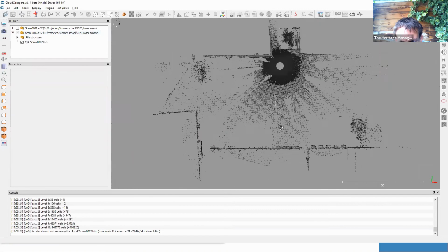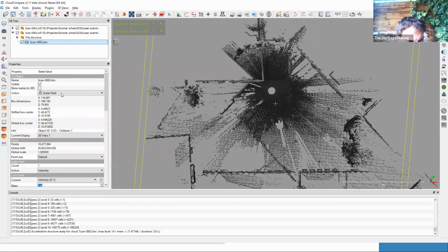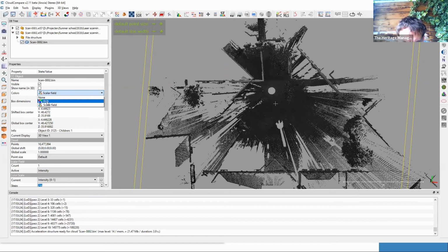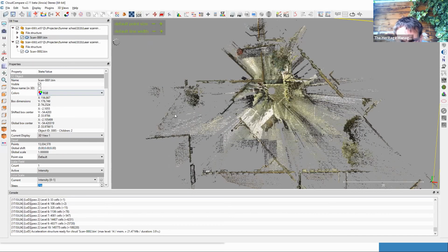If I visualize both point clouds again, you will see that I have a building here, I have a building here, and there's a lot of intersecting of walls. That's obviously because the rotation in the horizontal plane is totally random, and the orientation of the origin of both scans is situated here at the origin of my XY axis. So what I first do is I increase the visibility of my point clouds by setting my RGB values, so my color values.